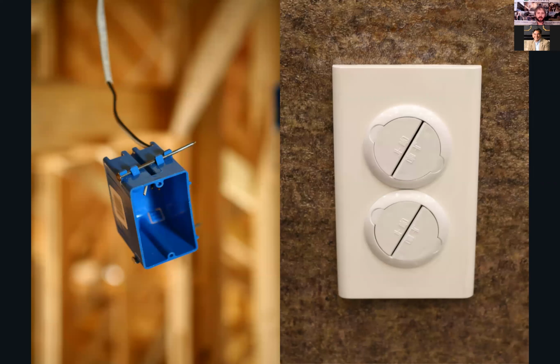For plugs, if you're putting in brand new plugs on an exterior wall, or you're renovating a wall that might be a little bit leaky, or you just have a basic wall, you can take the plug box out and buy an insulated one. Go ahead, in an older home, put your hand up to the wall and feel air coming in through that outlet, right? And these are a 2-for-1 if you've got kids, or your clients have kids. You can put those caps on and stop them from getting hurt. Plus it plugs those leaks, but it's still leaking around the box most likely. So the one on the left there, you want to seal up that whole box and stop those leaks. That's a great way to stop that airflow.